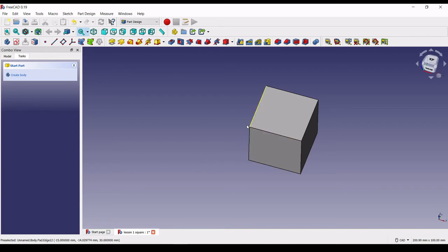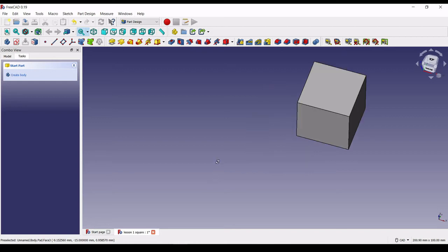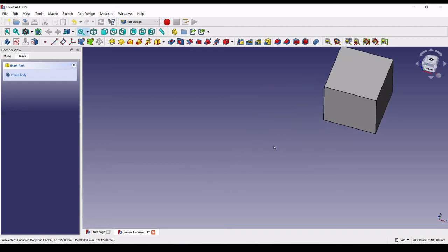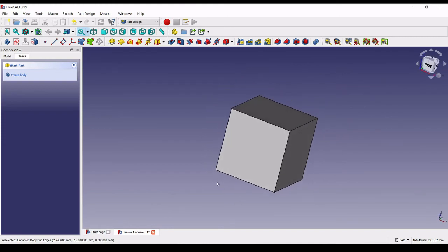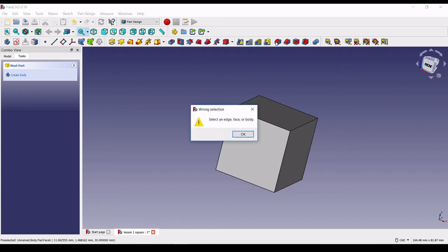To smooth the edges of my cube, I am just going to bring it back to the middle of there, and I'm going to turn it a little bit there. So to make a nice looking cube with smooth edges, we are going to click in the toolbar. We are still busy with bar design. You'll find one that says round, smooth, make a fillet on each edge, fillet. So you click on that one.